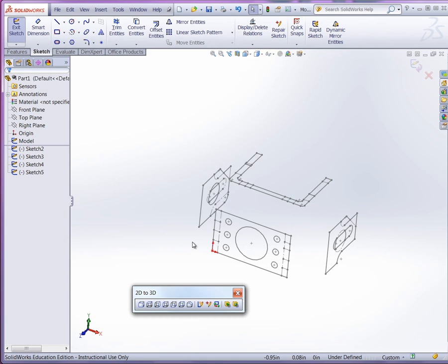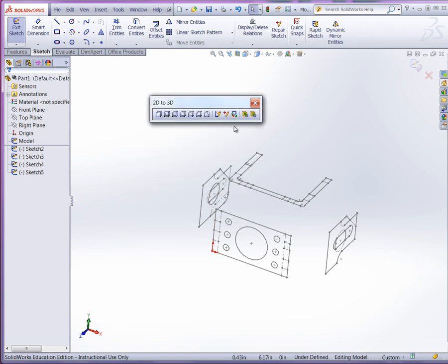Basically, you at least want to get them aligned by their profile lines. What I mean by that is we might want to pull this one and align it with this edge here. So how do we do that? If you take a look at the tools that we have, here's a line sketch, okay? And you could align a point from one sketch to another one.